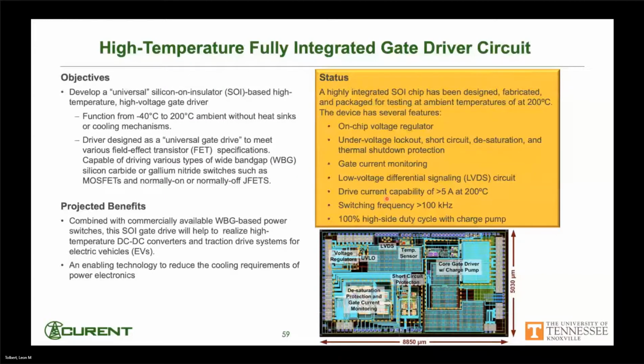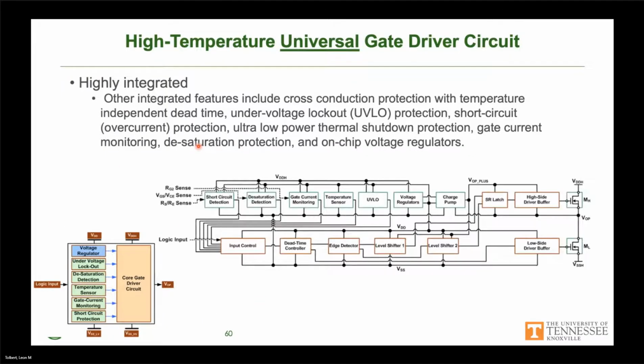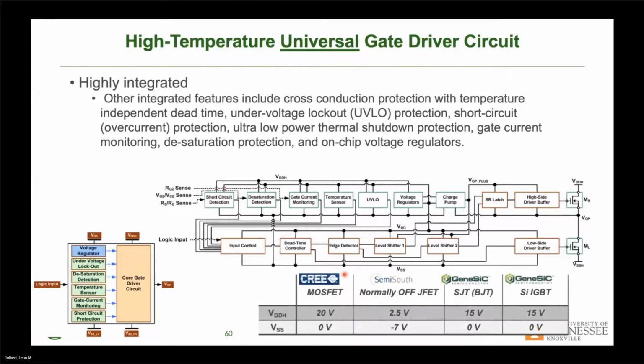But we also made it where we called it universal because we could switch many different types of power devices. So this is then going to show it more from kind of a circuit standpoint, all of these different things that we integrated there, and basically just different blocks of control, dead time, edge detecting, level shifting, charge pump, volt. So all of these different things, we were able to integrate.